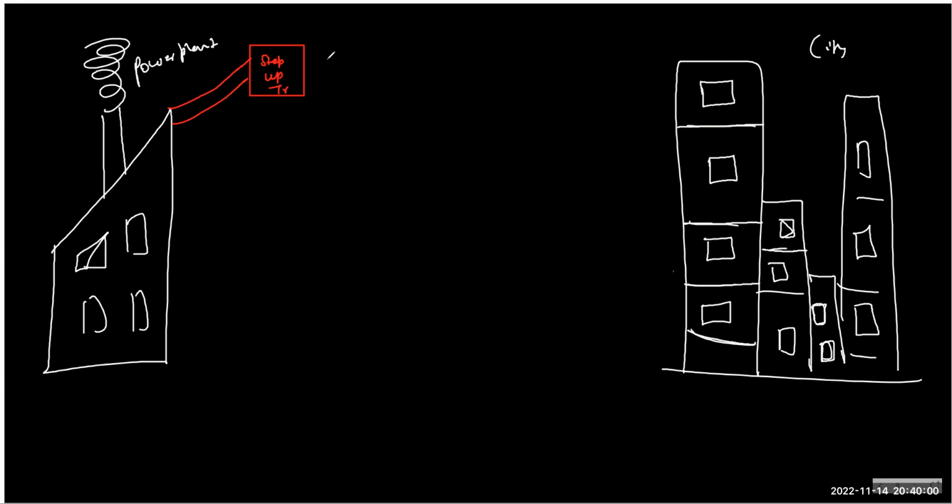Okay. So the first step is near the power plant, you step up the voltage with a transformer. Whatever voltage you're producing, you step up to a higher value. Here we have the coil turning, right? We have seen that the maximum value that you can produce by turning coil is NBA omega, if you remember. And the RMS you can produce is E max by root 2, by definition of RMS.